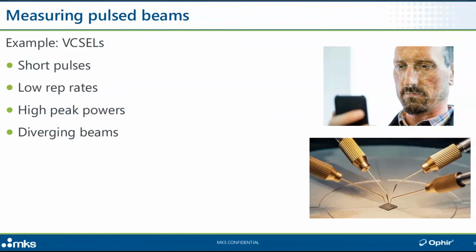These are used in proximity sensors, augmented reality displays, also higher power applications like LiDARs for autonomous vehicles or robotics and UAVs and things like that. So these are small devices, typically battery powered, so power issues can be critical in the success of an application or not. Combine that with a need to, let's say, project 30,000 laser beams onto a human's face, and it's kind of easy to appreciate the importance of measuring the relevant parameters and very tightly controlling them: power, very often also pulse shape, which is going to determine the resolution of distance measurement, and sometimes spectrum.